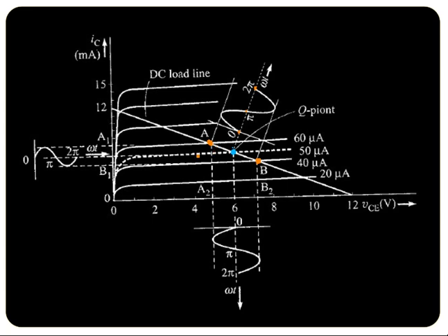Now, since the operating point is varying, we can plot the collector current from these data. If you project it towards the left on the y-axis, you will get the IC peak variation. You can see that because of the input signal variation, there is a variation in the IC also, isn't it? From the quiescent point. In the quiescent condition, IC is here, at the Q point.